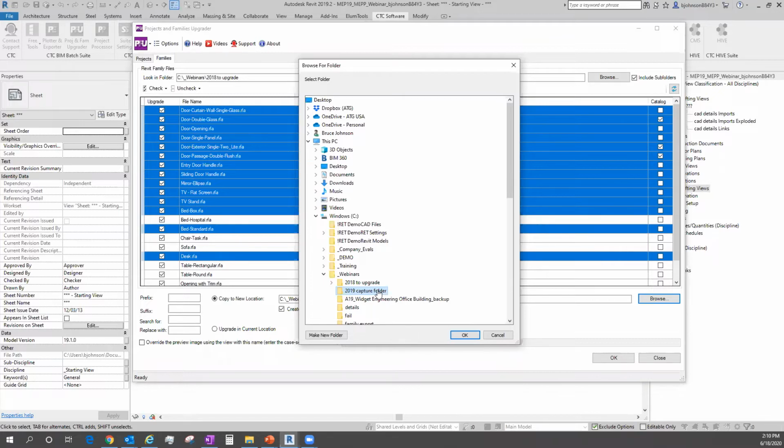Depending on whether you think that Revit's file paths on families are embedded in the family, you might want to put them in the final location. If they're not embedded in the family, then it doesn't really matter. But like our central files, obviously you'd want to put that in the real location and turn it into a new central file after detaching and auditing and all that. In the case of families, I don't think that's true. You can move them around at will.